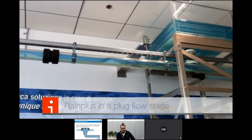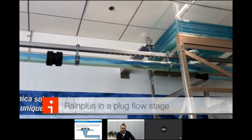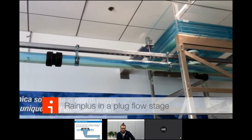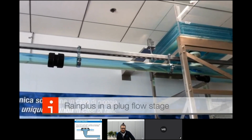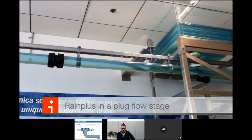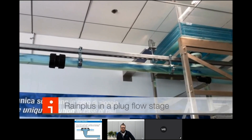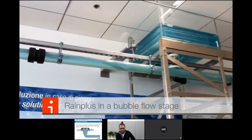Then when it starts to rain more, the water on the roof increases, and we enter the second stage, which is the plug flow stage. As you can see here, we have an increase of the velocity because we have the activation of the Siphonic effect, and then the system slows down again because we have the deactivation of the Siphonic effect. This is the plug flow stage. Then we enter the bubble flow stage.